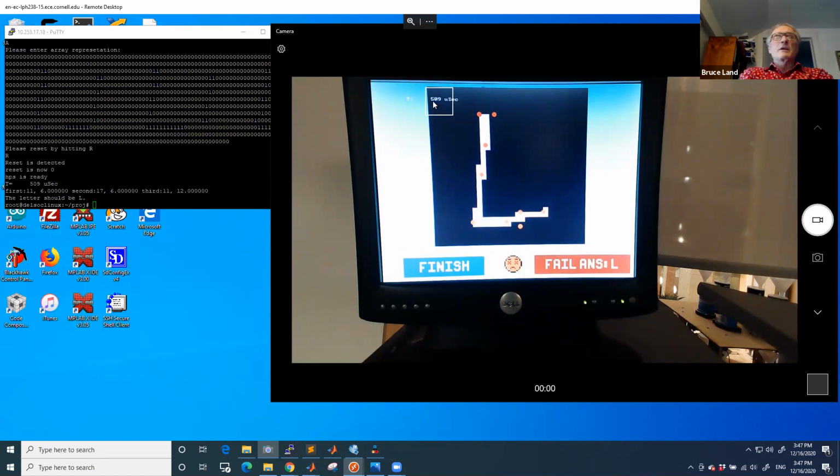The FPGA is much better. The power estimator tool will allow you to estimate your design power. All it takes is the compiled code. It doesn't take anything else. You could do it now. It could be a cool metric to include in a final report, just because it'll be impressive.